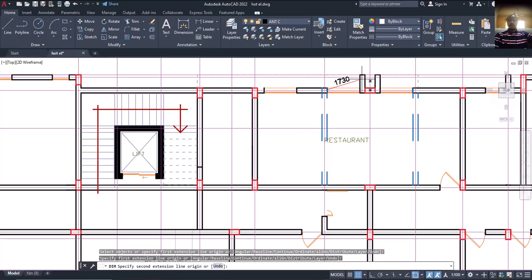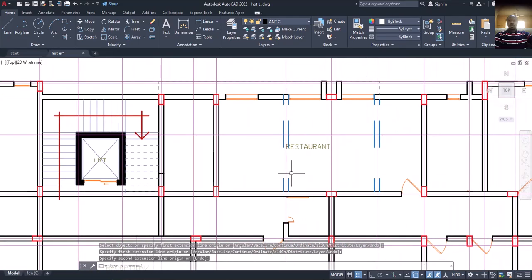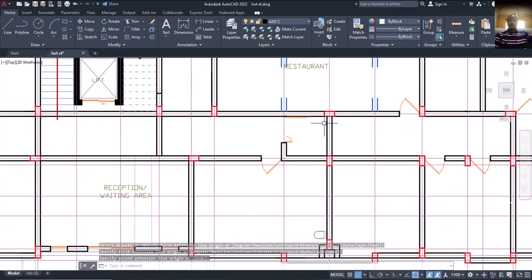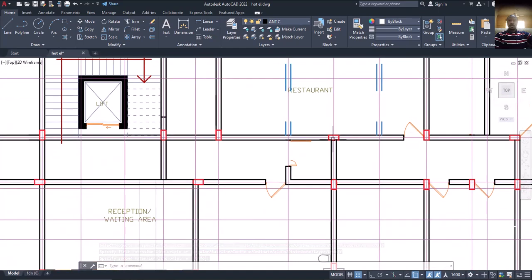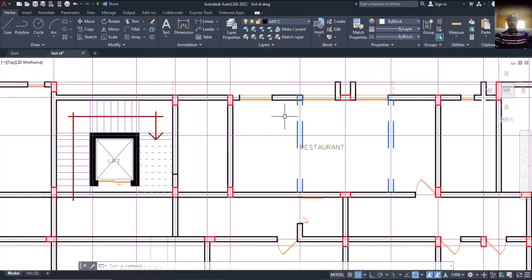And since it's 4, this one is just a dot. We can use a small beam to achieve this, or even slab. Slab can achieve this one for us. Let's see. Can put a small beam here, a beam here. Okay, so we can try to put a column here at this point and at this point, which means that in this place there will be no column here. Is that okay? So I think that one is better for us.